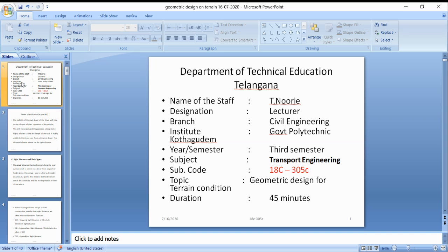That is the carriageway where the vehicle moves, and generally its width for national highways is 3.75 meters for a single lane, and 7.5 meters for two lanes without a curve. With a curve, it is 7.5 for the two-lane route.